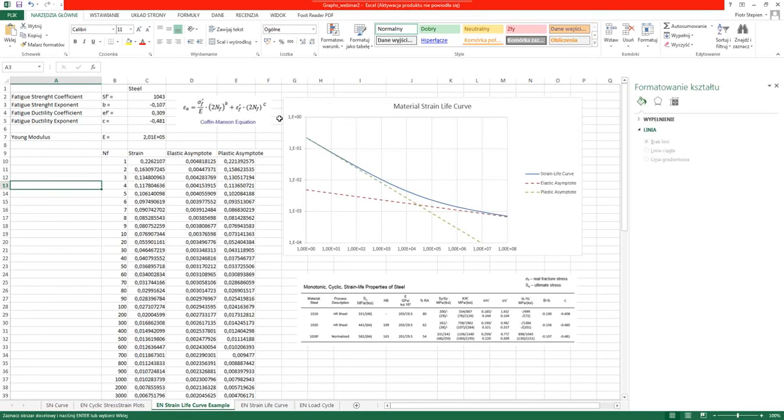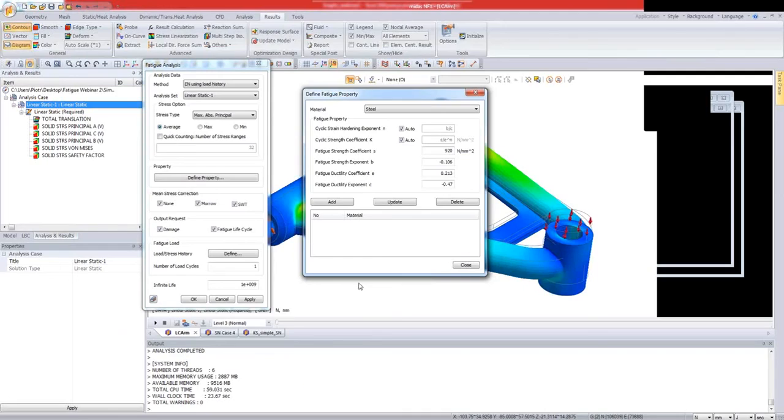Okay, as I said before, in order to calculate plastic strains, we will use Neuber's rule. I'm talking about this because now we have a curve, but we could use the nonlinear response of our model, using nonlinear static analysis, and create our curve as well. But today we are using this data. So now I'm switching back to MIDAS FX, and let's enter these values.